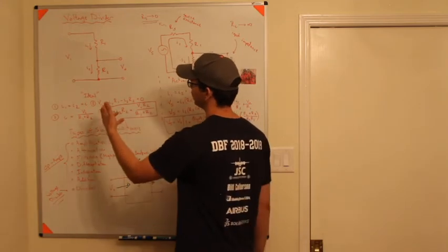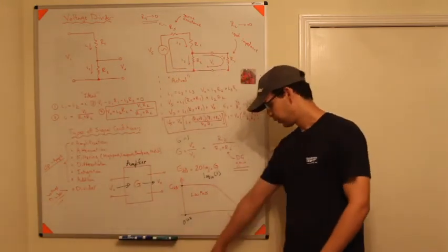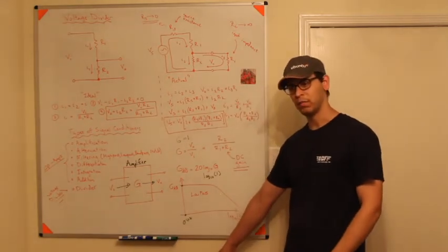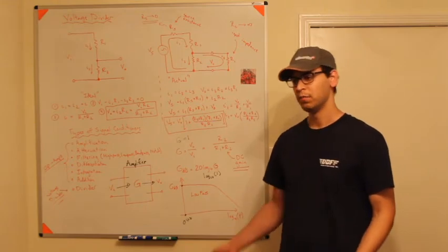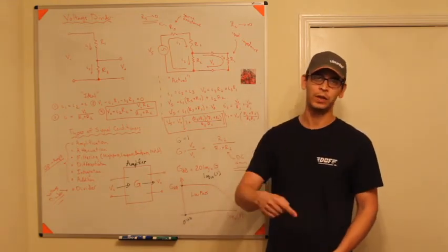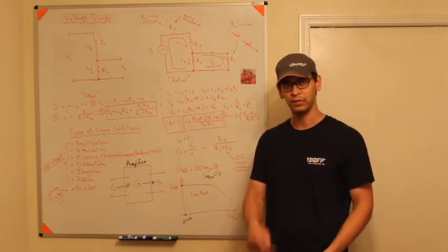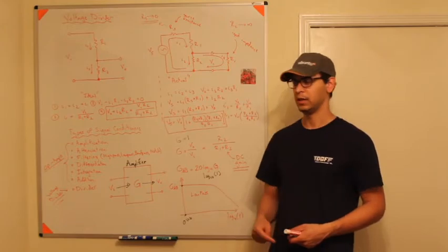And so let's talk about measuring this. You might want to do this in a situation where you have a 120 volt outlet that perhaps you want to monitor to see if you're always getting 120 volts. But if you hook up a 120 volt outlet directly to, say, an Arduino, which can only handle 5 volts, you would fry the Arduino if you did that.